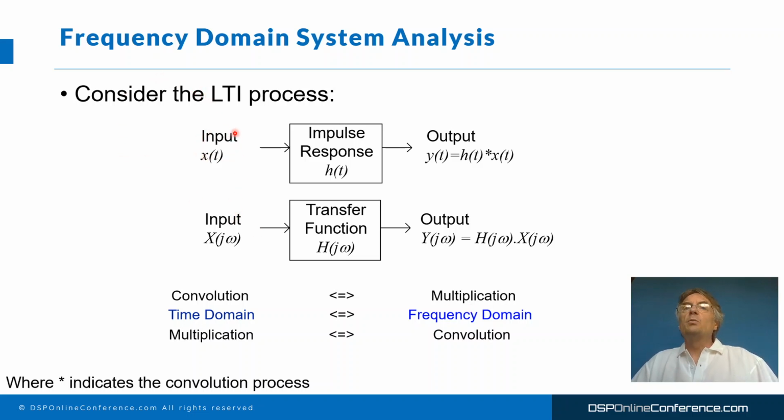So how do we do that? Well, we would need to transfer our time domain input sequence to the frequency domain using the discrete Fourier transform. We then can perform our operation in the frequency domain, which is a simple cross multiplication, dot product of the two vectors. Then we can convert our frequency domain result back to the time domain using the inverse fast Fourier transform, and now we have our output.